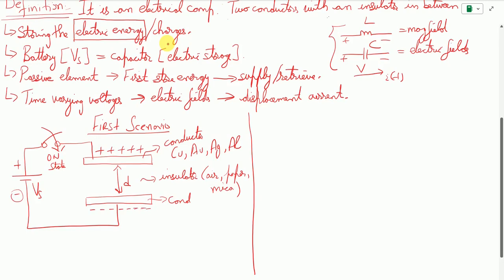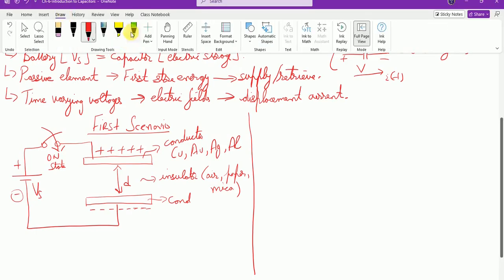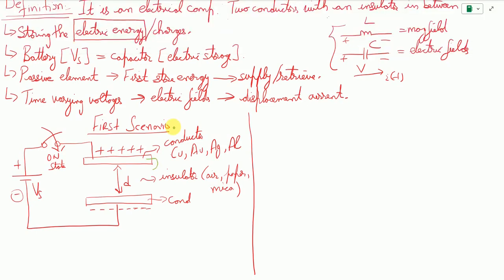So if we take a DMM and place it over here to figure out what is the voltage available. Let us say we want to figure out with a measuring tool what is the voltage appearing across these two terminals. So we might get a voltage of V1. So this is the voltage that is appearing. Interestingly, if there is a voltage available, how is the current going to flow, because these two conducting elements have an air gap represented by D between them?